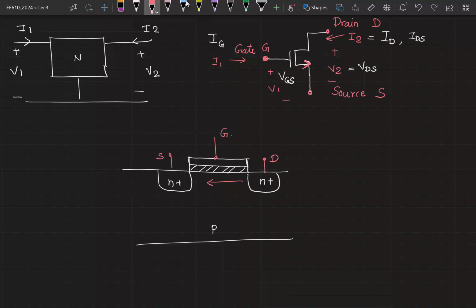Right? So this terminology is a little confusing. Current is starting from drain and it is going towards the source. Why did that come out to be? Because the naming convention is not with respect to the current, but is with respect to the charge carriers. For an NMOSFET, the charge carriers are electrons, and they go from source and end at the drain. So that's how the source drain convention has come out to be.